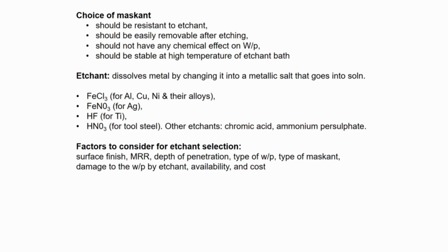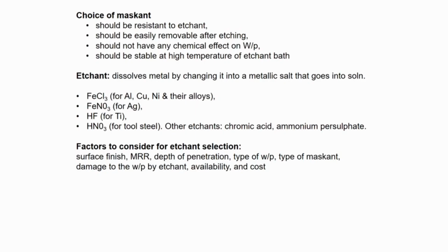There are different choices of masking. The masking should be resistant to the etchant, should be easily removable after etching, should not have any chemical effect on the workpiece, and should be stable at the high temperature of the etchant bath.